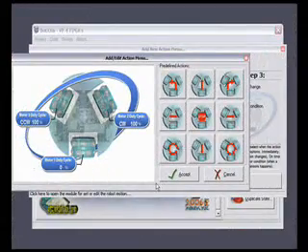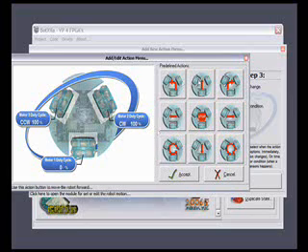Each MayaBot has omnidirectional movement capacity, that means it can move according to the results of the vectorial movements of each engine to achieve a movement in any direction. To ease the movement configuration of the robot, 9 predetermined movements have been established, represented by the buttons on the right side of the window. Moreover, we can modify them to create our own movements, establishing the power and direction of each one.